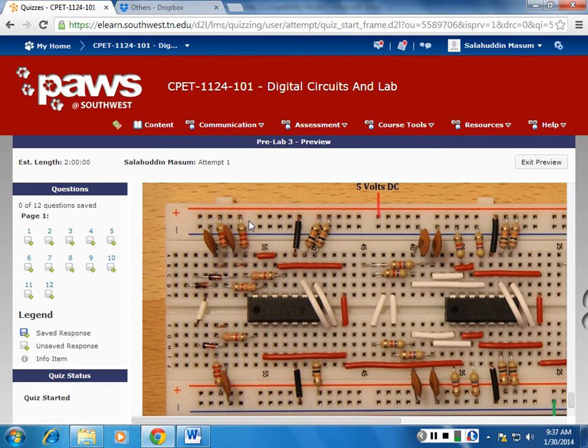That's how we use the top row, because we just connect the voltage 5 from the station, and then we use every single hole, or whichever hole you want. It doesn't matter, because you can keep some holes blank, or you can extend from whichever is closer. To run every IC, there must be a pin which will need voltage 5. It will be defined in the layout. I'll show you the layout again from the slide or the manual. We did that manual today as well.